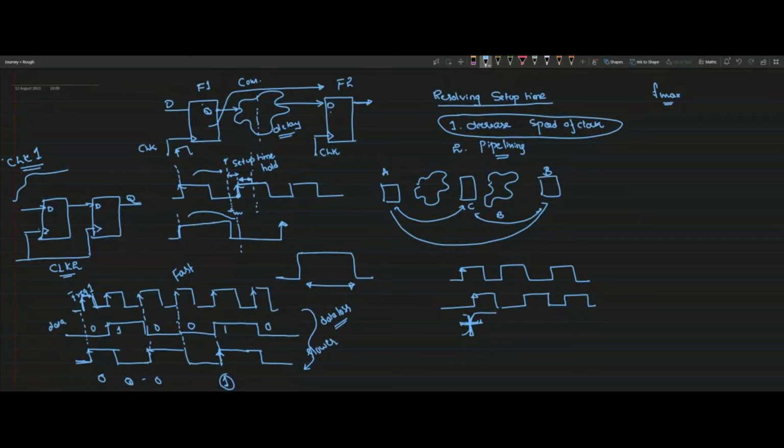What is going to happen is the same data will be captured multiple times, right? If I send one pulse at this clock, making it high and then low, at this clock edge what will it do? 1, 1, and 0. So instead of a single 1, it is capturing twice. So multiple times it will get captured.